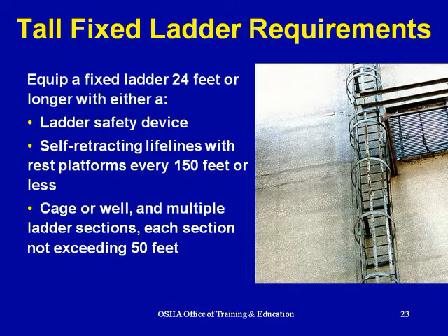Tall fixed ladder requirements. Equip a fixed ladder 24 feet or longer with either a ladder safety device, self-retracting lifelines with rest platforms every 150 feet or less, cage or well, and multiple ladder sections, each section not exceeding 50 feet.